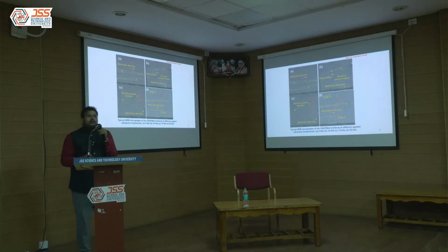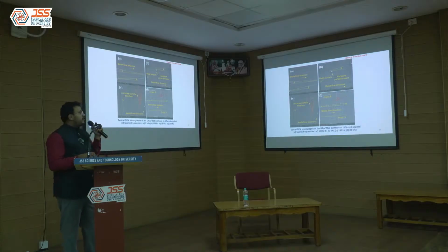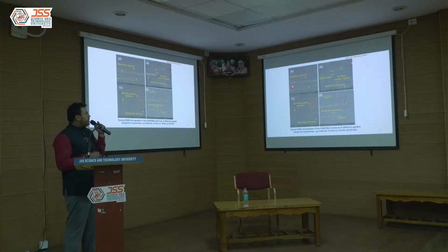Okay, so coming to proof, under the microscope we observe that when the media is flowing on a cylindrical surface, it is not flowing in a straight line, it is moving at an angle theta, and that media flow direction has been changed when you vibrate the workpiece at high frequency, and the abrasive particle impact and the deep scratch formation is observed during the ultrasonic assisted abrasive flow machining.